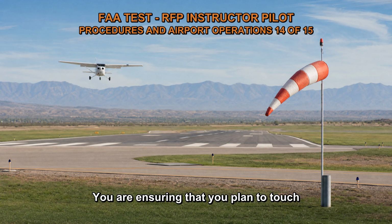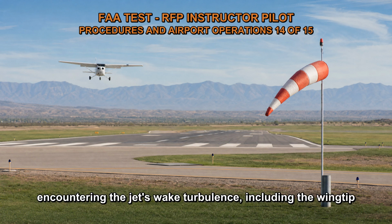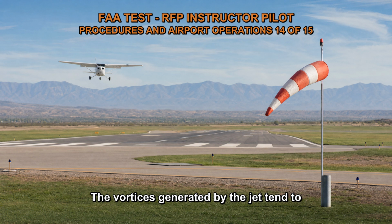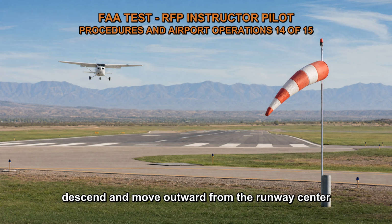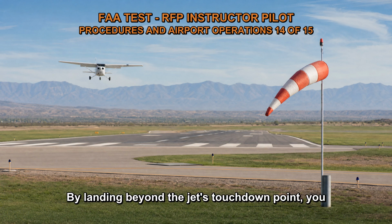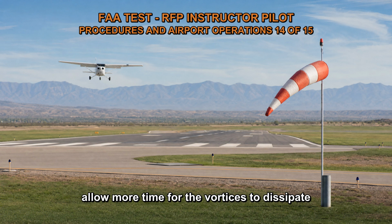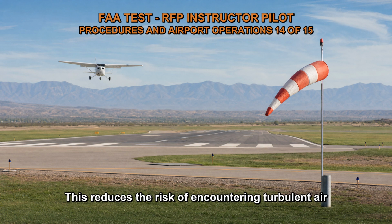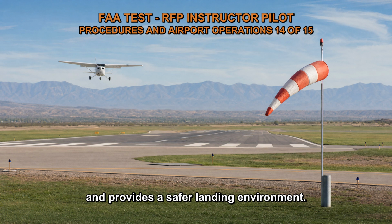You are ensuring that you plan to touch down beyond the jet's touchdown point. This means that you aim to land farther down the runway than where the jet has landed. By doing so, you reduce the likelihood of encountering the jet's wake turbulence, including the wingtip vortices. The vortices generated by the jet tend to descend and move outward from the runway center line. By landing beyond the jet's touchdown point, you allow more time for the vortices to dissipate and disperse before your aircraft reaches that area. This reduces the risk of encountering turbulent air and provides a safer landing environment.